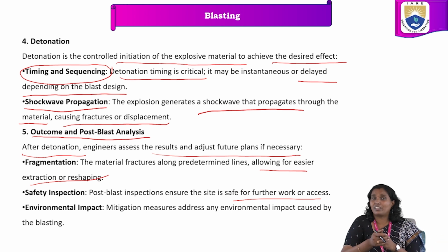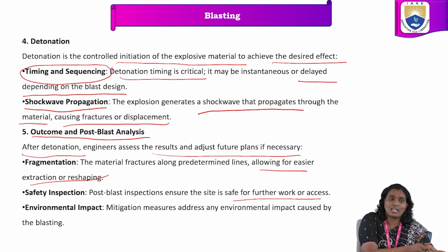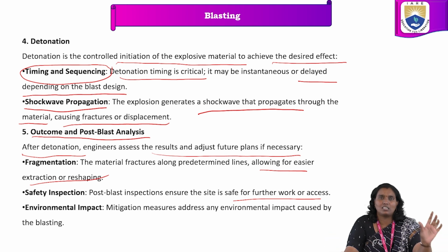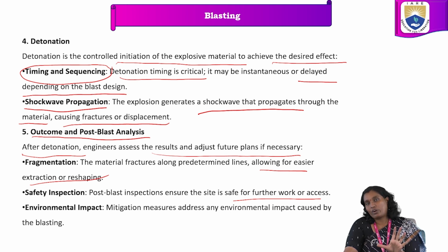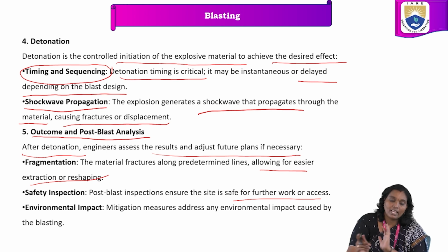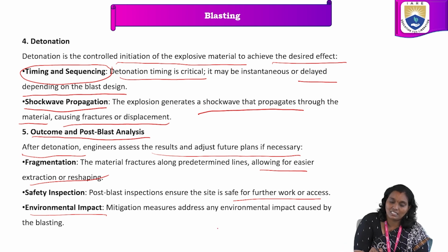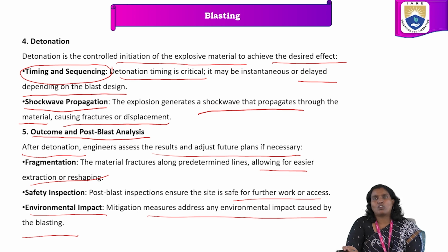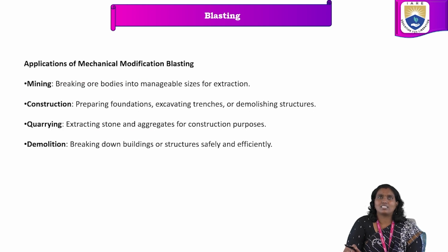It depends on the different scenarios, how it blasts, and next to the blast, how the surface area and the locality are. Each and every parameter is very important. Post-blast inspections are very important for continuing the work in that particular locality. The environmental impact is also very important. Mitigation measures address any environmental impact caused by the blasting. That is one of the things we have to understand.